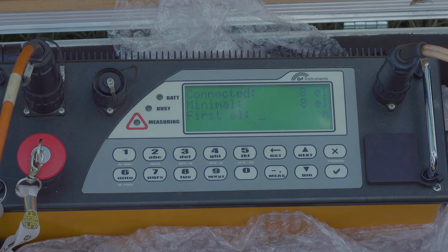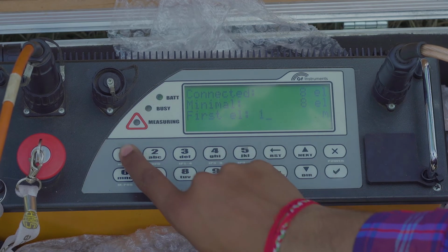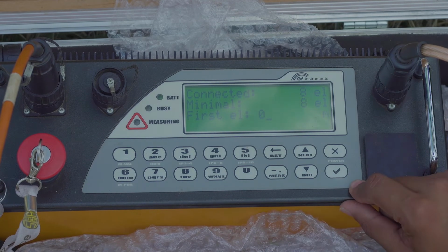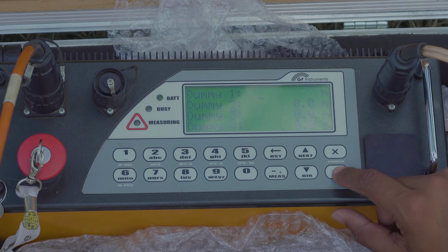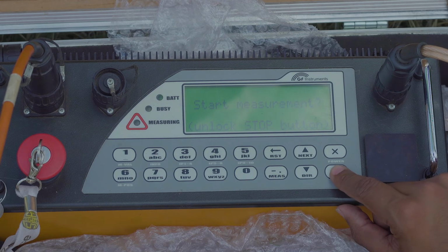We then continue to measure now. From here, we turn on the battery, and this gives us the survey specifications. We then set where the first electrode is, and this is at 0 meters. We then continue as we have no electrodes which we would want to discard on the screen. From here, we keep our screen as is, and we start the measurement where we unlock the start button.